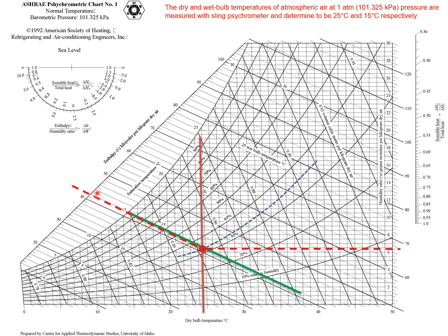And next is you want to find your relative humidity. To find relative humidity, it is between 30% to 40%. Now you've got to estimate, draw a line which is parallel to these two lines, all right? So this is the blue line that I've drawn. So this is parallel, and then you estimate between 30 to 40 here on your appropriate scales that you can find, what is the value of this line. So it seems like it is between 33 and 34%.